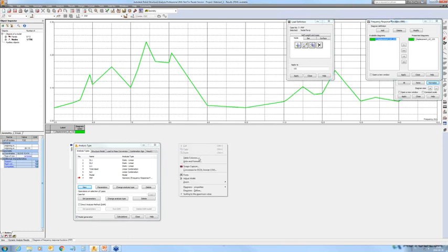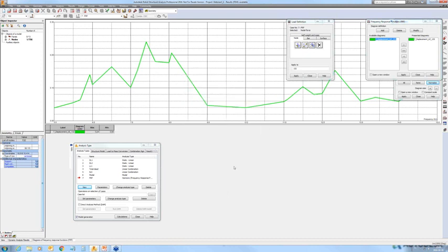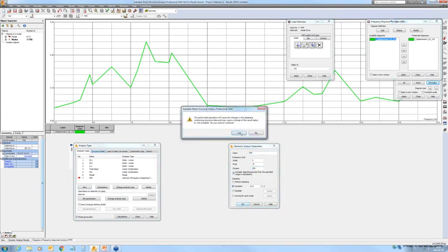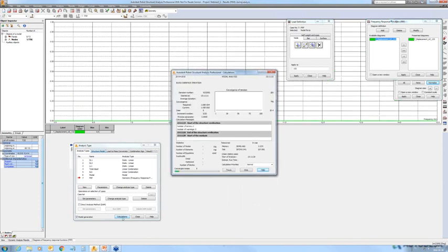And in addition, in the table column, I'm going to add the information about maximum and minimum value that we obtained. Okay, so now if I go to the parameters of FRF analysis, I can change this number of divisions to larger, for example, 200. And if I recalculate the model, the diagram should look much nicer.